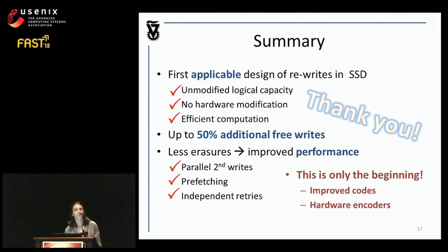Okay, so the thing is that indeed Flash is very complicated. So first of all, you have to notice that when we write the second writes, we do it in the same order as the first writes. But again, indeed there may be some disturbance between the new data that we write and the old data. This is something that we've just started to experiment with and needs some further experimentation. But in the worst case, we can always use just the lower pages, which then should not cause much disturbance.